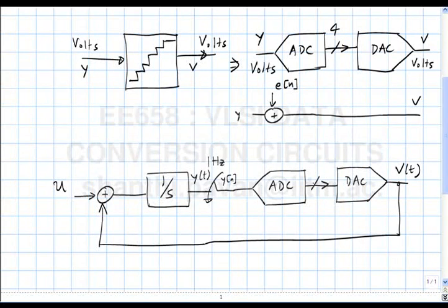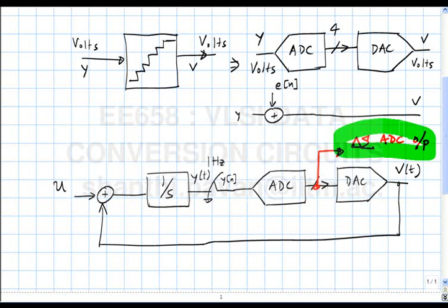See, please note that this is an analog to digital converter. I want analog input, voltage in and bits out. So this is the delta sigma ADC output. So, if I had just a 1-bit quantizer, that is 2 levels, what will the output be? What codes will it consist of? It will consist of either 0 or 1.